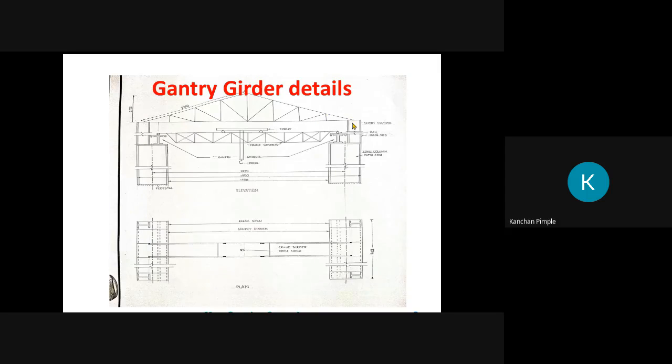Then you have to draw as per the scale this ISMB 100 column, and show the thickness of flange. The thickness of flange we know from our design. Below it again is ISMB 500. So 500 is the width, and these two lines are the width of flange. So first you draw this truss with the short column and long column. Then you can go for showing the details of crane girder, trolley, hook, etc. As per the scale, you have to convert it.